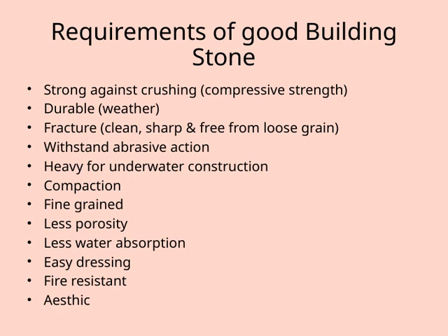For underwater construction, heavy stones are preferable because they stay in place and resist buoyancy. Proper compaction during quarrying or placement ensures stability. Fine grain structure and low porosity are important because they reduce water absorption, making the stone less susceptible to damage from freeze-thaw cycles or moisture.